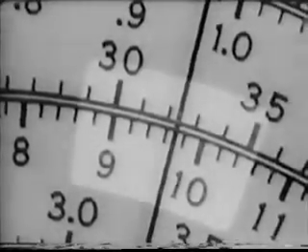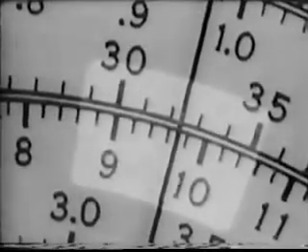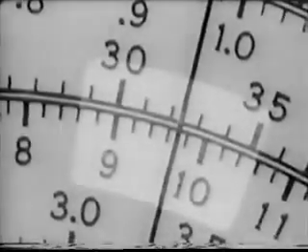The voltage between the points is 9.70 volts. The points were set at 1.25 centimeters apart. So the field in the bar is 9.70 divided by 1.25, which is 7.76 volts per centimeter. With this fixed field, we can show that the delay time is directly proportional to the distance from the source to the detector. To show this, I will connect this constant speed motor to the microscope stage.